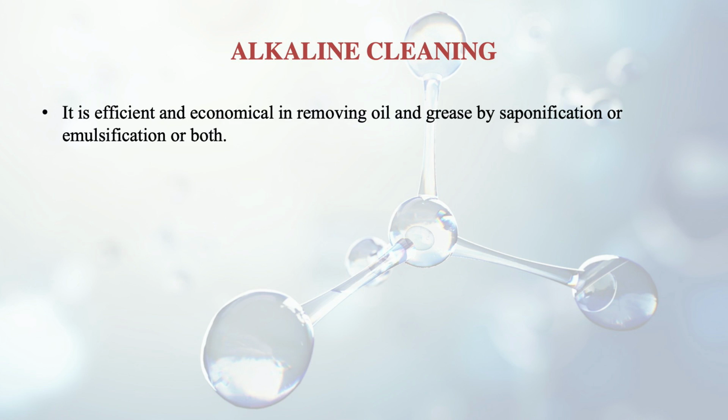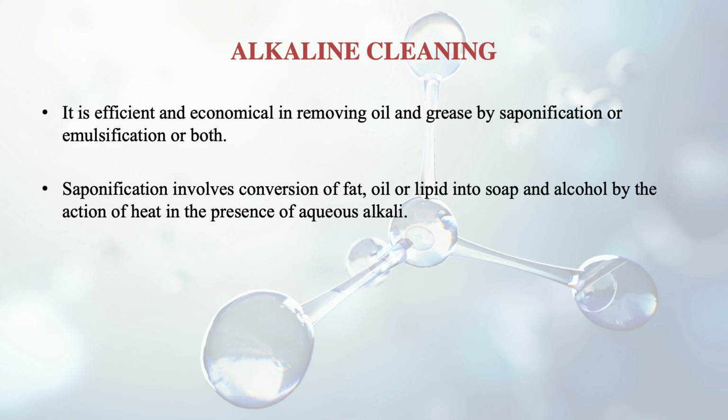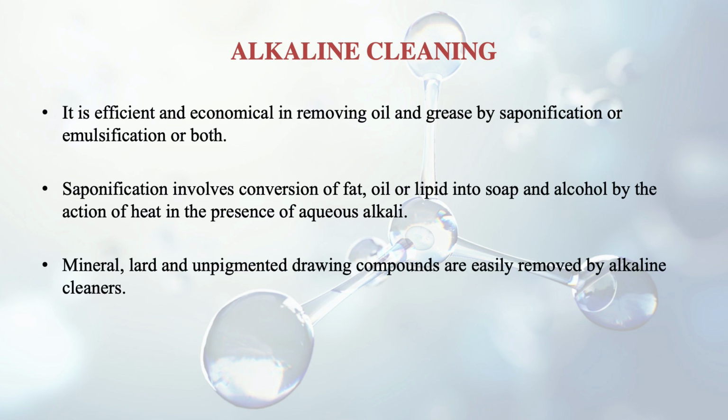First of all, alkaline chemical cleaning. This one is quite efficient and economical in removing oil and grease by the saponification or emulsification process. What is saponification? It involves conversion of fat, oil or lipid into soap and alcohol by the action of heat in the presence of aqueous alkali. Mineral oil, lard and unpigmented drying compounds are also very easily removed by alkaline cleaners.